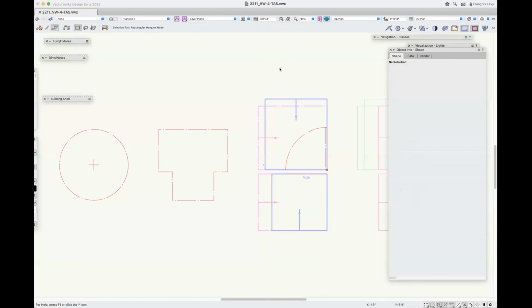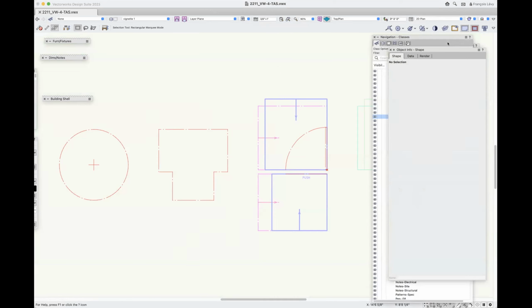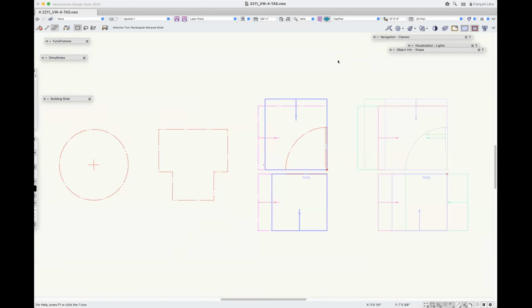Switching gears, this is just simple as a box of rocks. And I have Dwayne Mann to thank for some of this. I got some of these symbols from him, gosh, years and years ago, and they're just so useful when laying out commercial spaces. I just use them all the time on commercial projects. First of all, it's okay to make a symbol of a 5-foot turn radius, or an alternative, a wheelchair turn path.